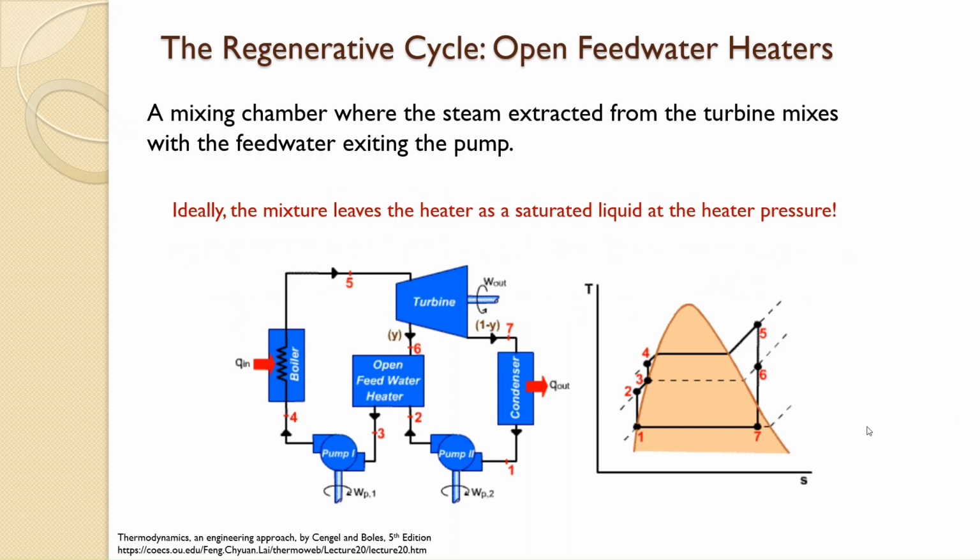In an ideal situation, the mixture after the open feed water heater leaves here, state number 3, leaves the heater as a saturated liquid at the heater pressure, which is the same as the pressure of the extraction.